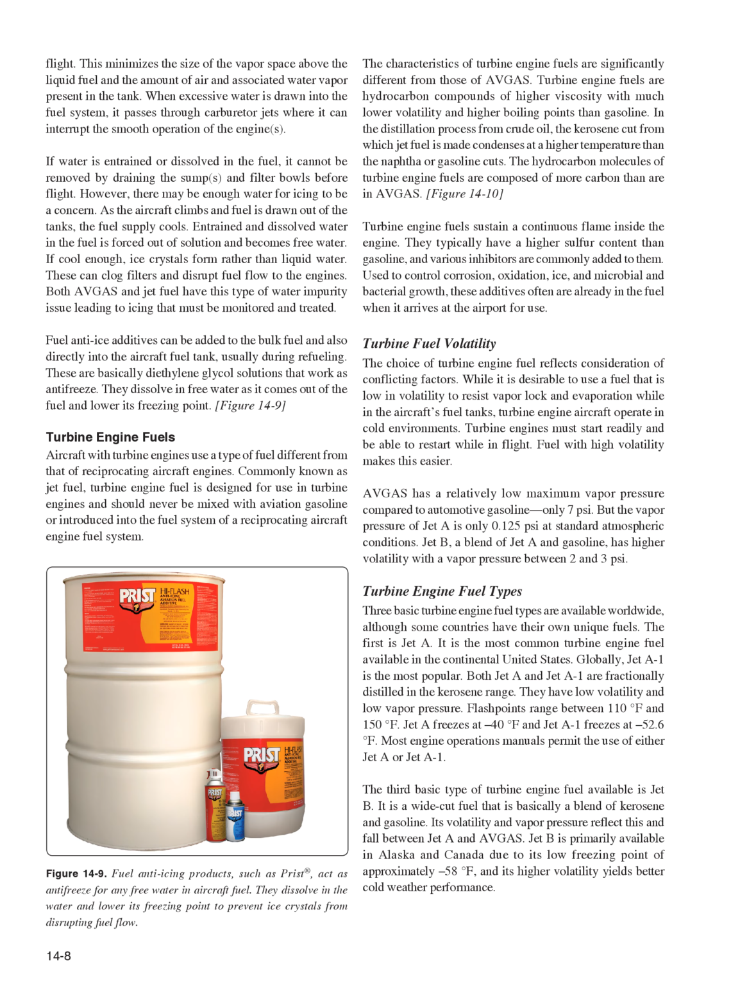Turbine engine fuel types. 3 basic turbine engine fuel types are available worldwide, although some countries have their own unique fuels. The first is Jet A. It is the most common turbine engine fuel available in the continental United States. Globally, Jet A1 is the most popular.